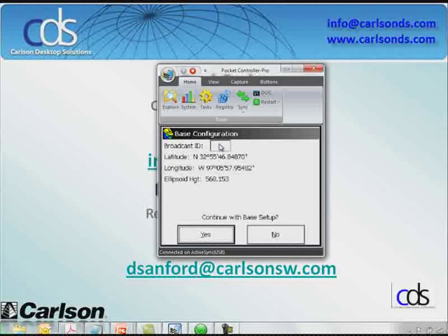Let's say I'm doing a 10-mile road project, and I don't want to move a base every afternoon as I go. So maybe I set up control along the project, and I set different bases up along the project so I can have people working in different areas at different times. If I'm setting up multiple bases, I can give each base a broadcast ID, and then when I go to the rover, instead of telling it to just find the nearest base, I can tell it to go to this specific base ID.